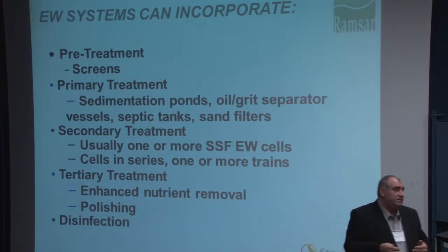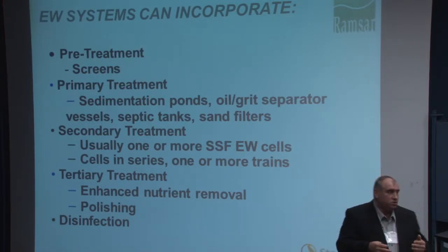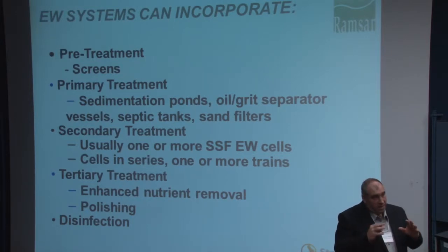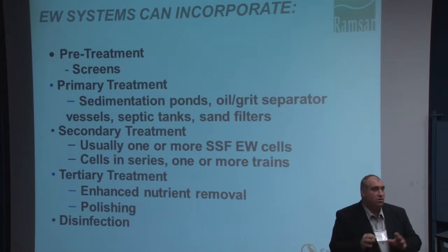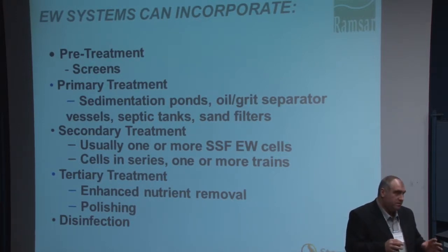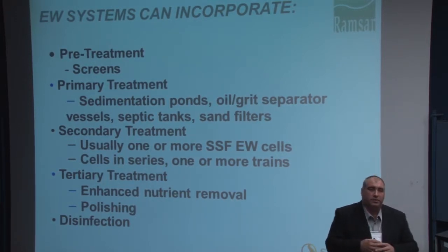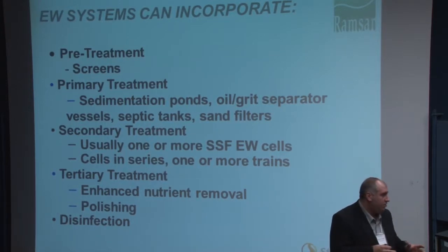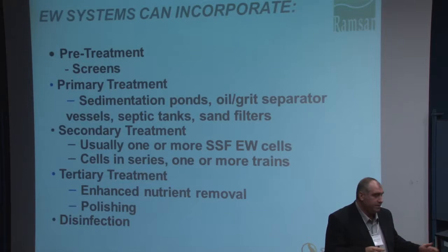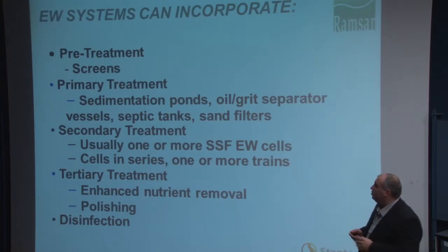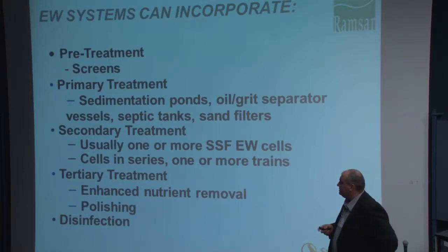And the reason is it's a wetland. So you're moving water in most instances through a media. And you don't want that media to clog and to end up forming preferential pathways or limiting the ability for water to move through that media. So that's your primary treatment phase.